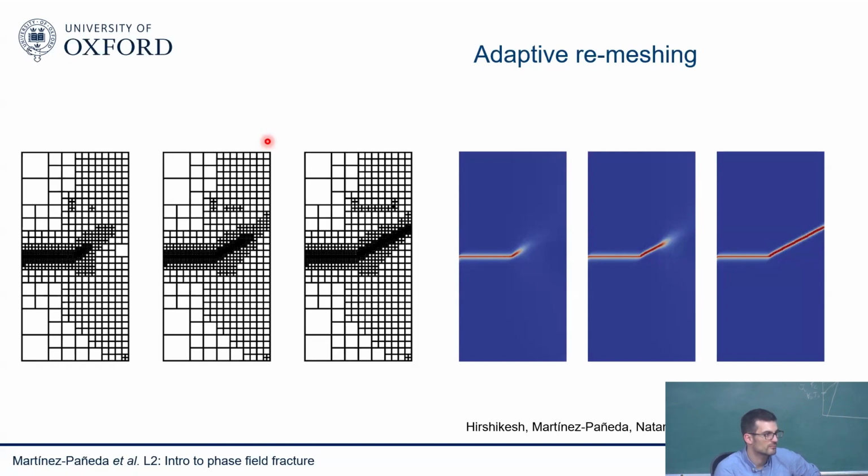So how does it work? Well, you solve another degree of freedom, right? So it's similar to displacement. You will get a value of the phase field in the nodes, and then you interpolate within your element. So similar to displacement field, any other quantity that you solve. Similar to temperature. If you solve for temperature, it will be the same as solving an extra equation where temperature is varying non-uniformly in your component. Instead of temperature, it could be phase field.